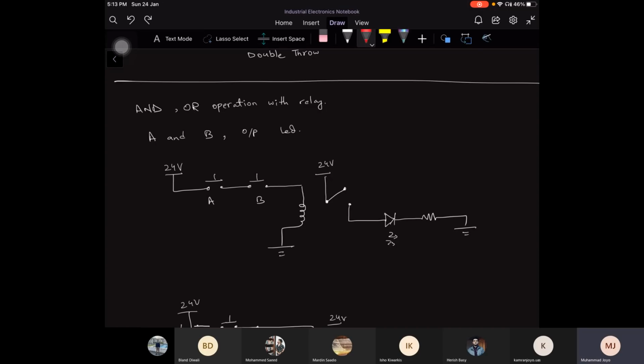So how was the switching occurring over here? The switching was occurring due to the electromechanical phenomena. Once you provide the signal at the input side, the coil is energized, and due to that, the bar at the output side goes from normally closed to normally open, right? So input has no relationship with the output electrically.